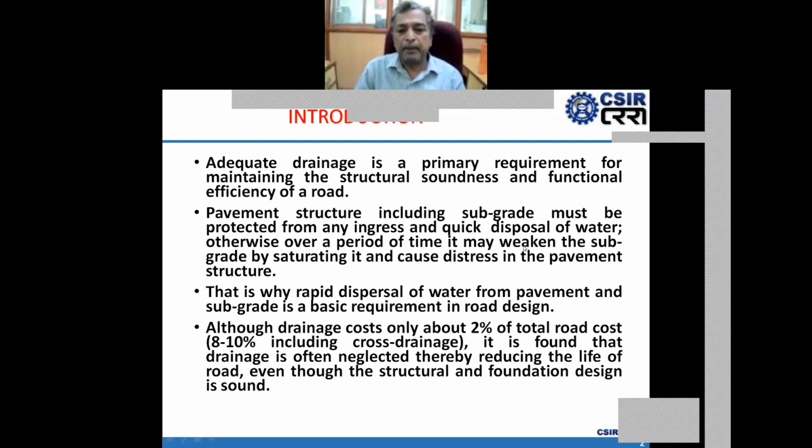The pavement structure, including subgrade and other layers, must be protected from ingress and quick disposal of water from the pavement. Otherwise, over a period of time, the subgrade will saturate and distress will occur on the pavement structures. That is why rapid disposal of water from the pavement and subgrade is a basic requirement for proper road design.